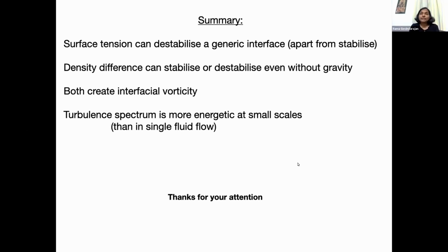Actually, that's a brilliant question. We know that viscosity variations do things to interfacial instabilities, namely the Rayleigh-Plateau instability. The Rayleigh-Plateau is typically written down for inviscid flow, but when you put in a viscosity contrast in addition, it becomes the Rayleigh-Tomotika instability, where the viscosity jump can actually increase or decrease the growth rate of this instability. But we haven't studied it in 2D. We've been focusing on very high Reynolds numbers, but even at those Reynolds numbers, if you have a significant contrast, I do expect something to happen there, Bala, along the lines of the Rayleigh-Tomotika.